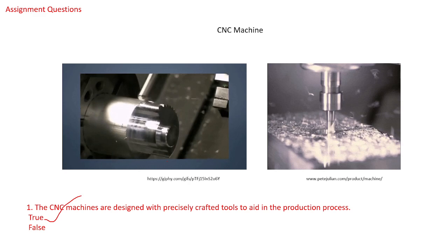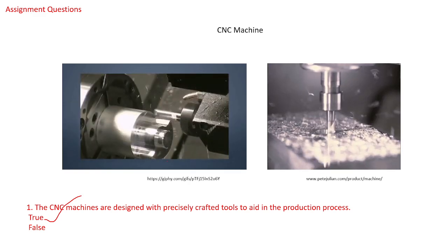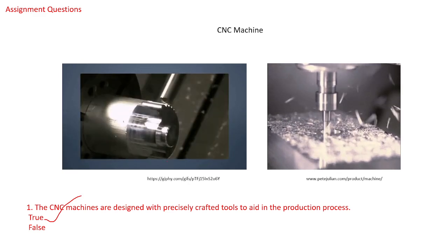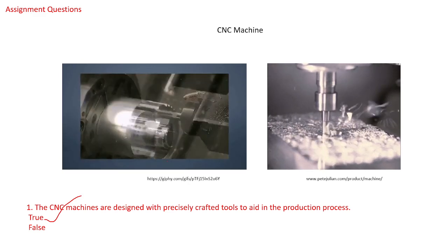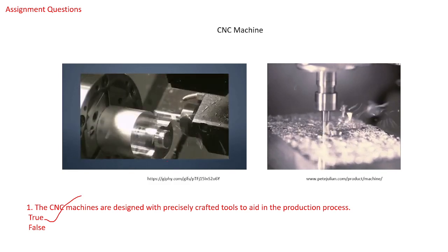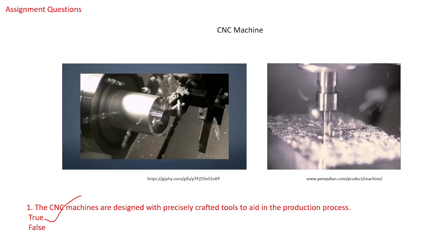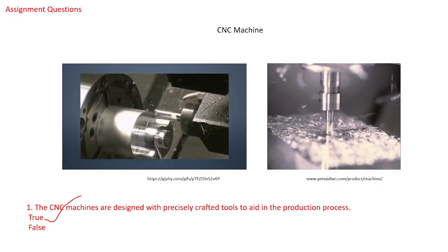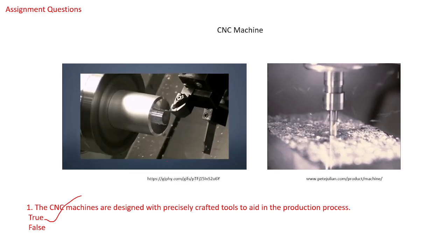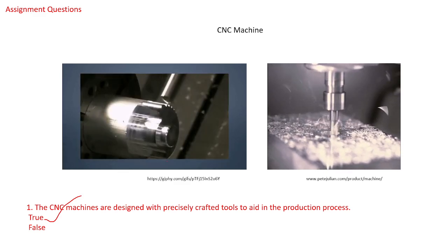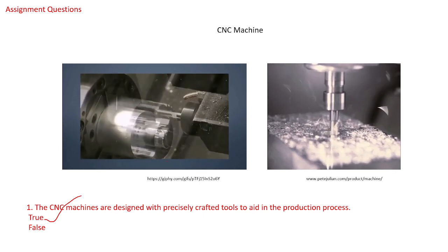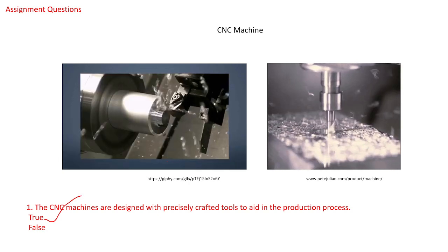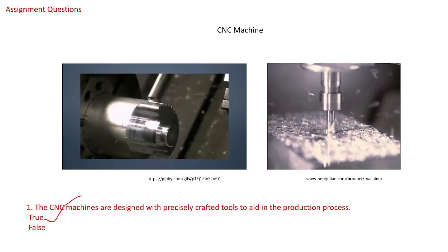Basically, it depends on the end usage, and another is your joining mechanism. For example, if a bearing is there, a bearing will always be very, very precise. General components, which are non-rotating, will generally be of medium accuracy. You can always take it like this, whatever I am saying.